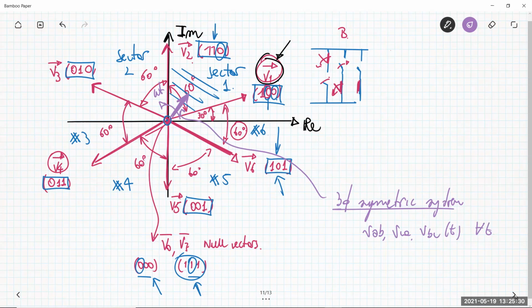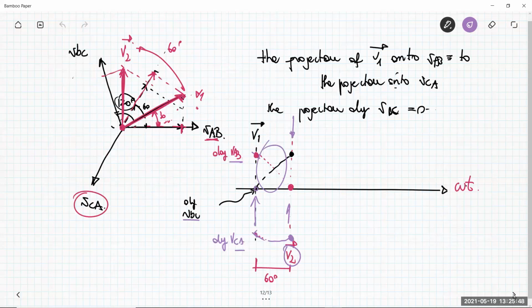And then from the other side, we have a three-phase inverter that, depending on the combination of the switches inside the legs, can generate only fixed positions, those indicated by the space vectors, and that represent a specific discrete time interval. So the goal is to use the space vectors that represent fixed positions to synthesize the rotating vector.